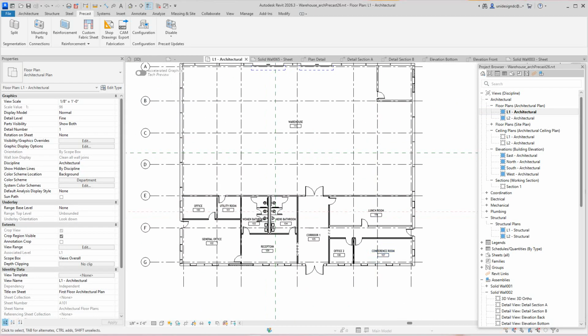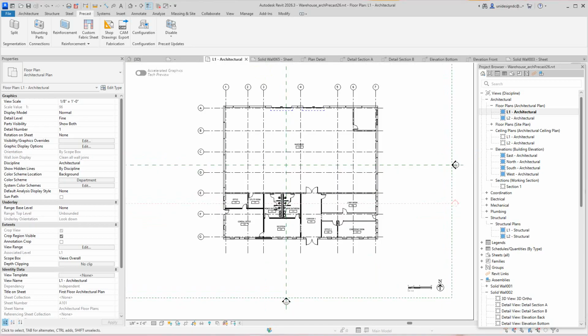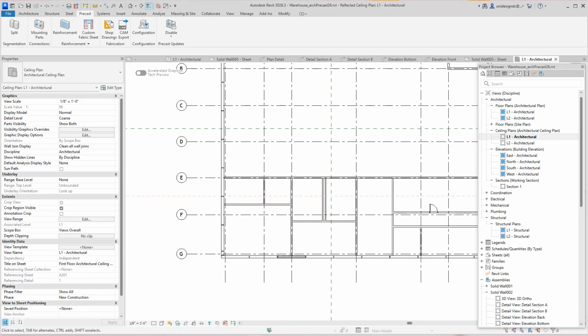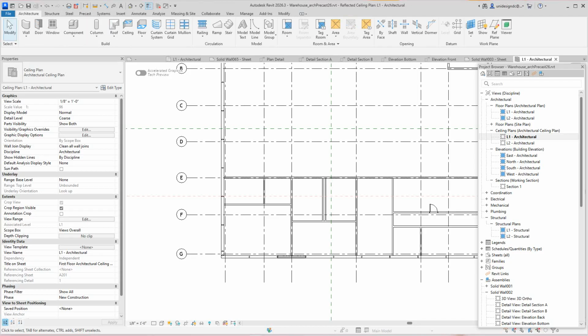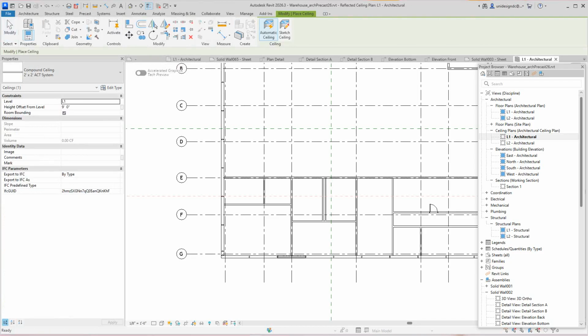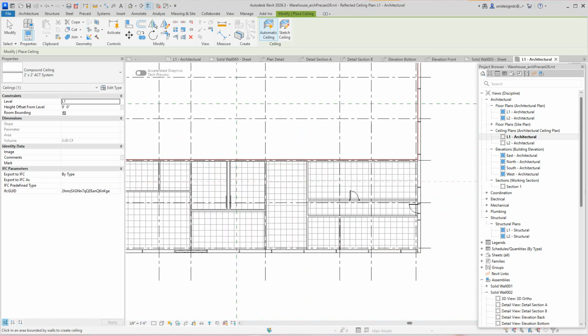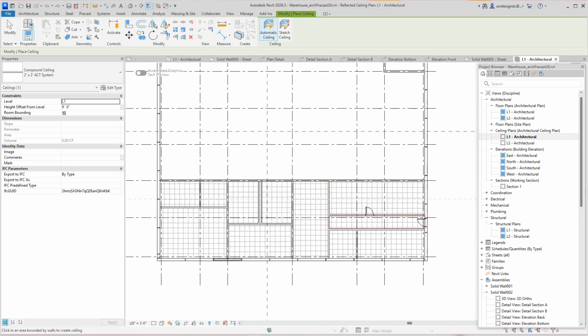So might want to start on my ceiling here. So I'm going to go just for the electrical purpose. I'll get started with that here. So I will go to my level 1 ceiling, which is here. And I'll go to architecture, ceiling. It's going to be a 2x2, and I'll go there, there, and there. And there's my ceiling. Probably got 2 in that one. Sorry. Yep, and there's my ceiling.